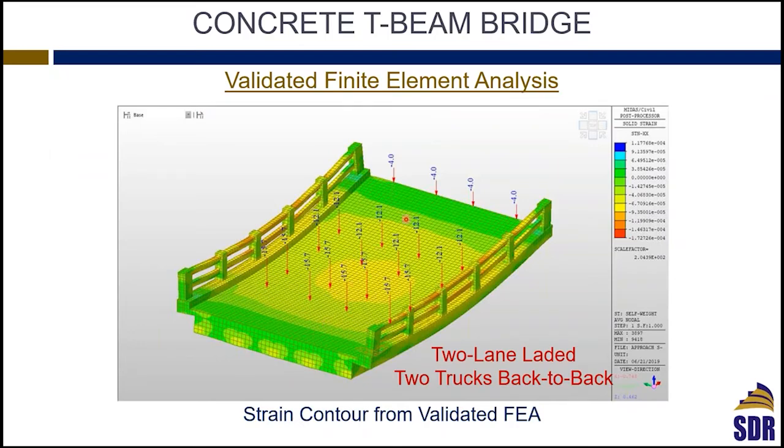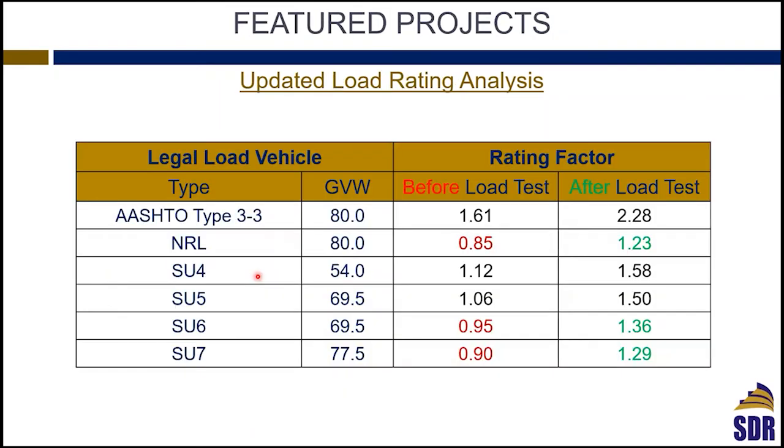You can still see that, as we always expect, the bridge will mainly bend in one direction. However, if we look at the strains as well and the deformed shape, you'll see that bridges always have the dishing action, so they're more of a 2-way bending action. Again, it depends if the load is symmetric or non-symmetric, if you have the barriers and what the structure type is, but always what we assume is 1-way bending action. Sometimes it is aggressive for bridges, but it depends on the structure type.